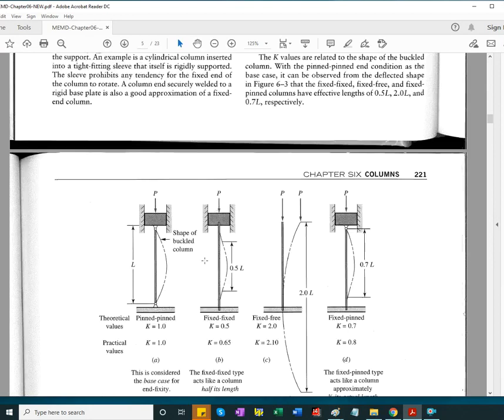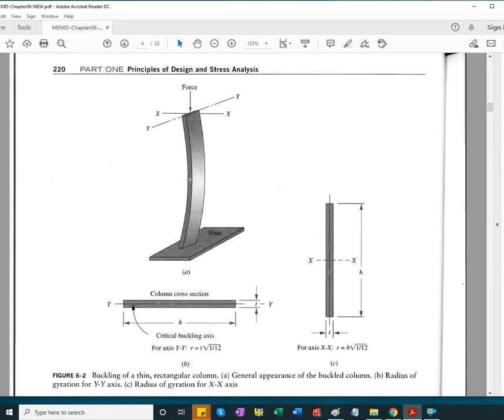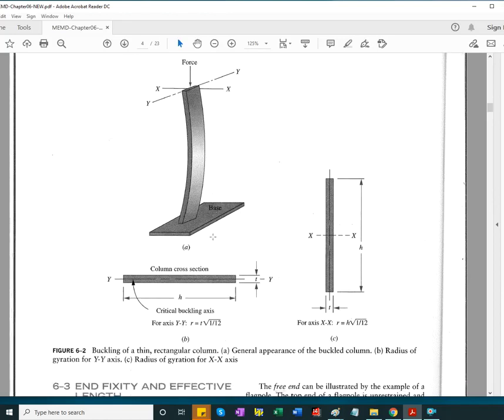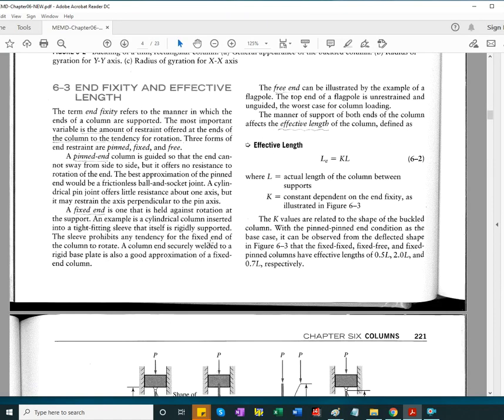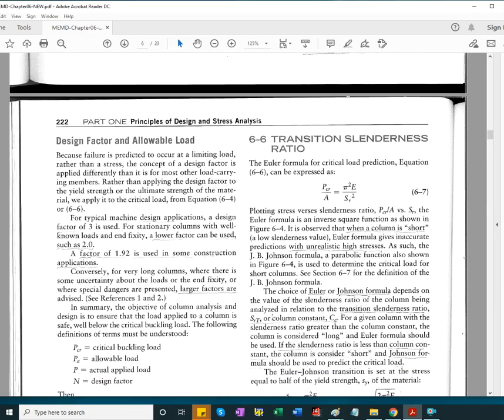Euler theory does not capture the effect of exceeding the yield strength of the material for short columns. So if you calculate the buckling force for a short column, and then the compressive stress that the critical load can generate in the column, you can get very large compressive stresses, and corrections are needed.